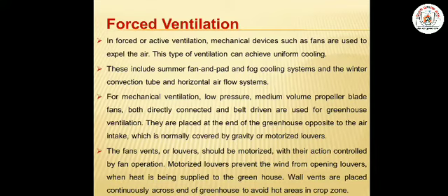Motorized louvers prevent the wind from opening the louvers when heat is being supplied to the greenhouse. Here, the wall vents are placed continuously across the end of the greenhouse to avoid hot areas in the crop zone. One example of that forced ventilation is the fan and pad cooling system.